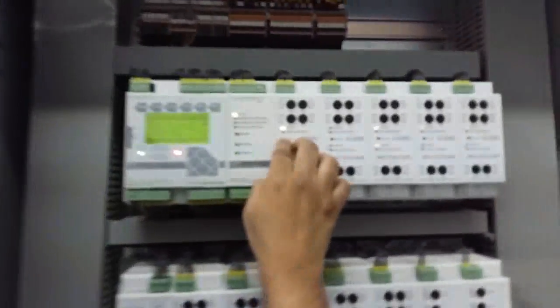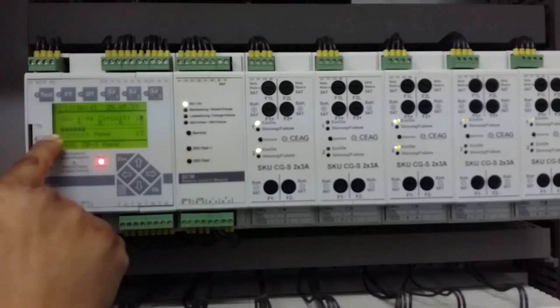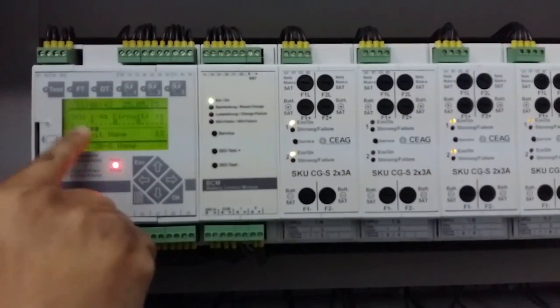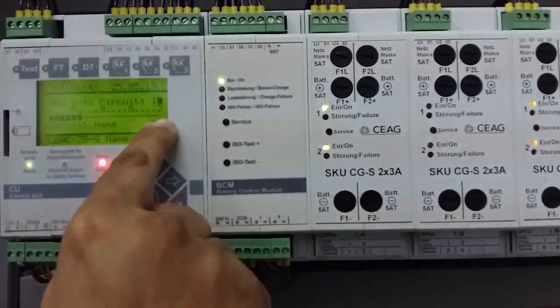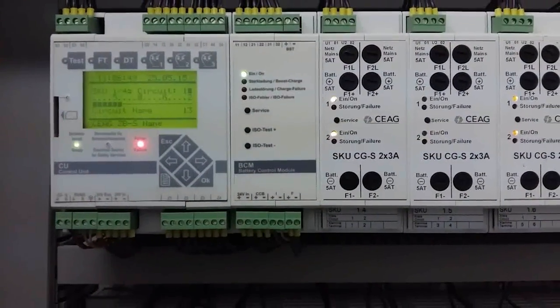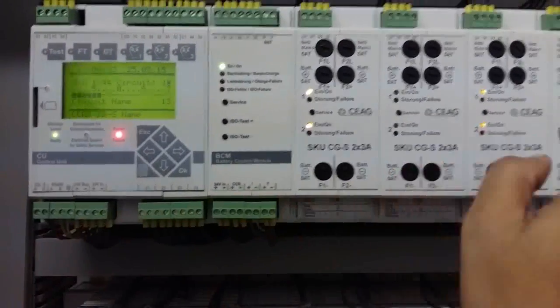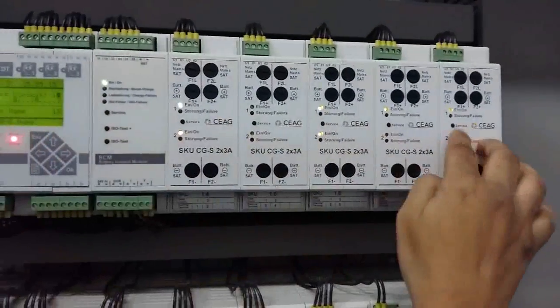Let's start here, the service button. If you can see, when I press this service, it gives the indications that some fixtures are healthy. You see numbers 1, 2, 3, 4, 5 and 6, up to 6 are healthy. The remaining it is not giving because those 6 have been given addresses and all 6 are working, are operational.